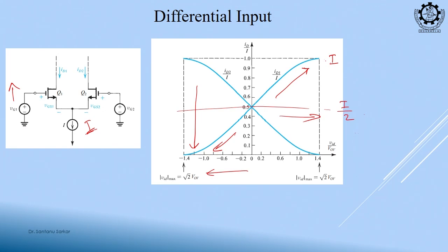This is the main advantage of the differential amplifier: both of the MOSFETs are symmetrical, the tail current is fixed, and RD of both branches is symmetrical. So whatever the output, they should always be symmetrical and out of phase. So, if one is increasing, the other should decrease.